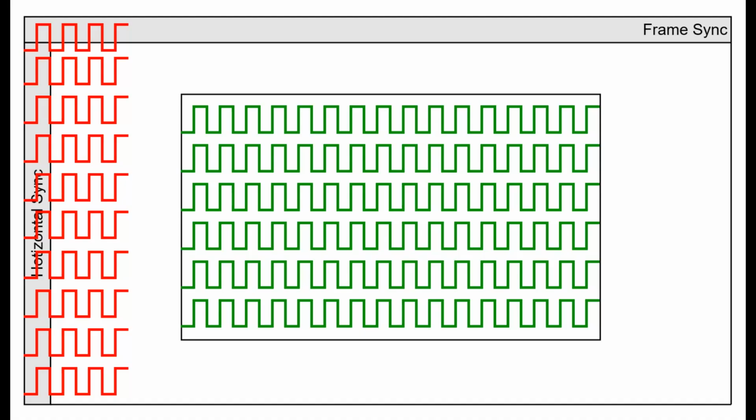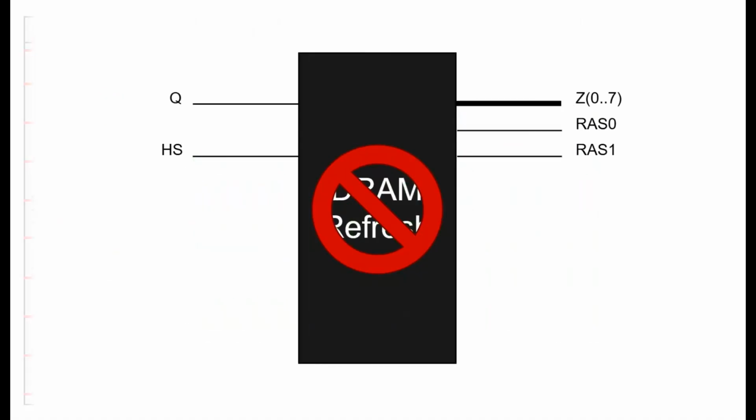But thankfully, the 8-bit 256 cycle chips were designed with this in mind and allow for a maximum of 4 milliseconds. Now that I've mentioned all this, the whole lot is irrelevant to this project. I'm specifying SRAM only, so there is no refresh cycle. That means no refresh counter. This also raises another point.